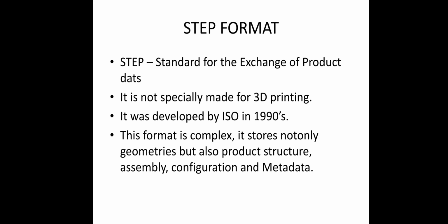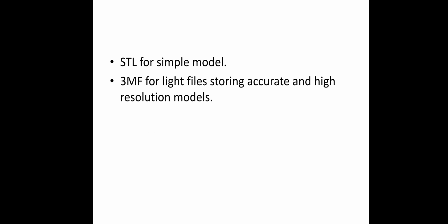This STEP format is sometimes used in additive manufacturing technologies, and if it is used there, it contains additional information. It was developed by ISO in the 1990s. This format is complex. It stores not only geometries but also product structure, assembly, configuration, and metadata. Some of the data which is not required for additive manufacturing is also present in this file format, so the file size is greater.